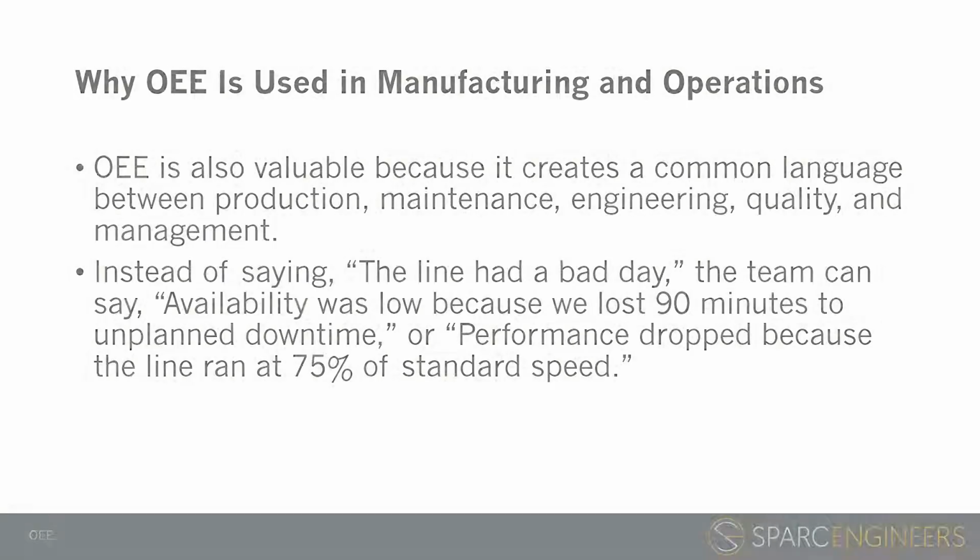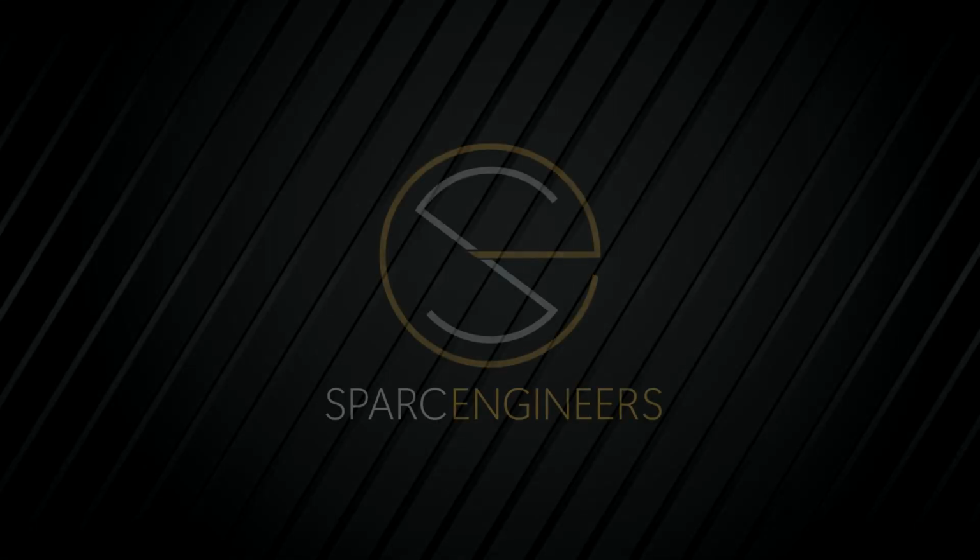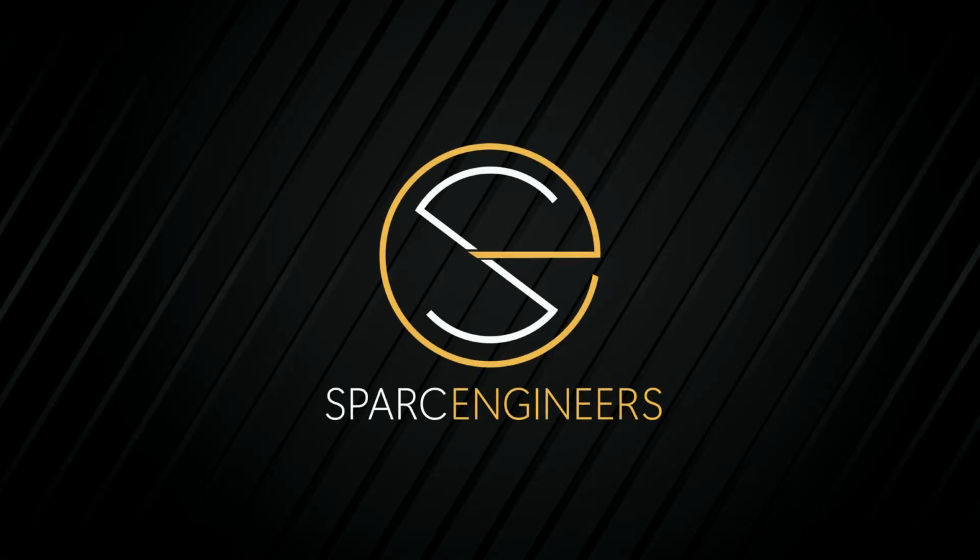The key takeaway from this section is that OEE turns general complaints into measurable losses. Without OEE, we may know that a process is struggling, but we may not know whether the real issue is downtime, speed loss, quality loss, product mix, changeover time, or repeated minor stops. With OEE, we can separate those losses and quantify them. Once losses are measured, they can be prioritized. Once they are prioritized, they can be investigated. And once they are understood, they can be improved.